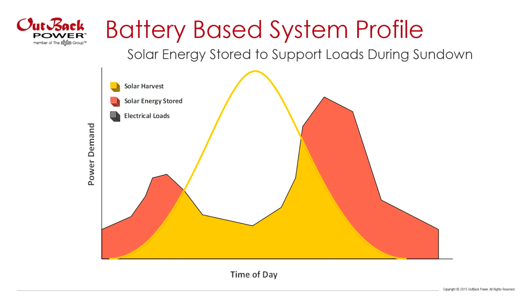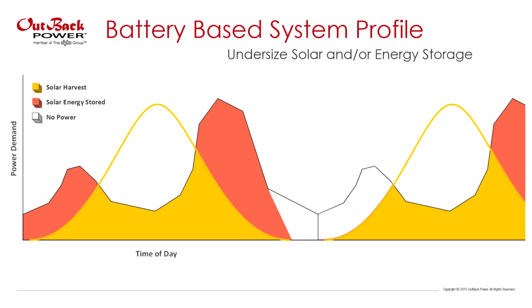If you were to undersize your PV array so that it doesn't fully charge the batteries, then you would run out of power and have an outage until the morning or afternoon. If you design the PV without any buffer, and let's say there's a cloudy day, you could also run out of power and run into this situation. So make sure you're designing to the worst case.